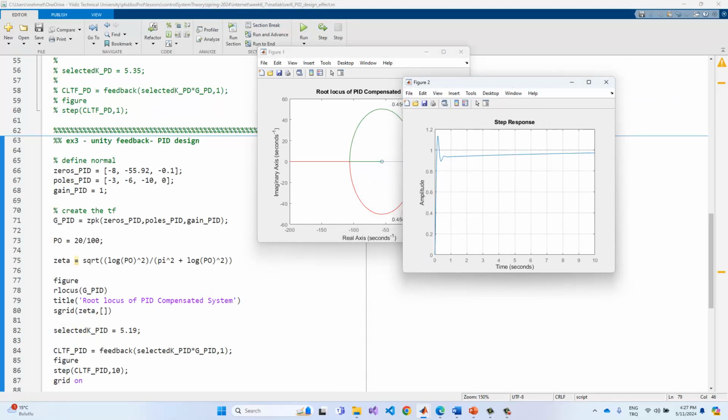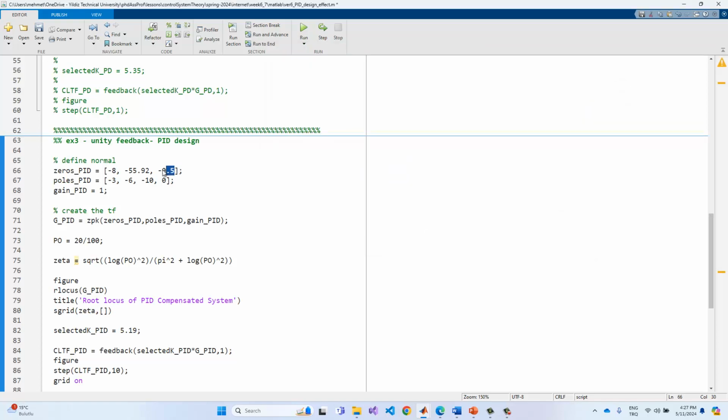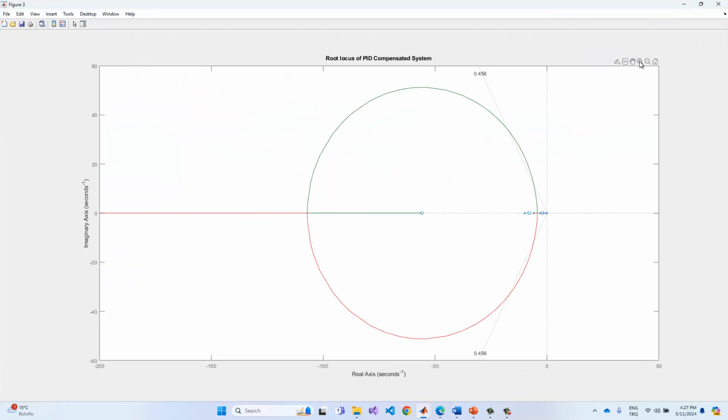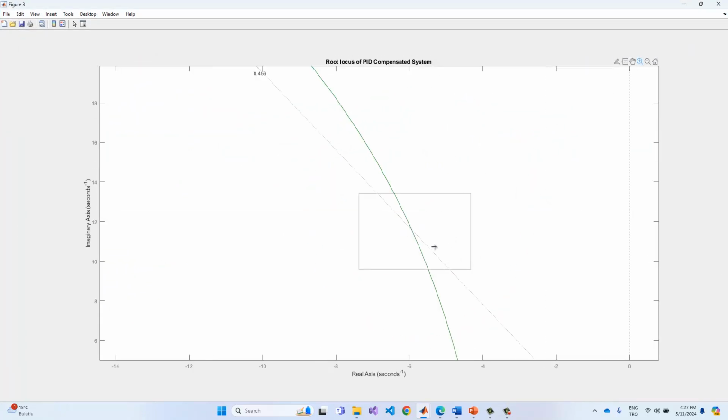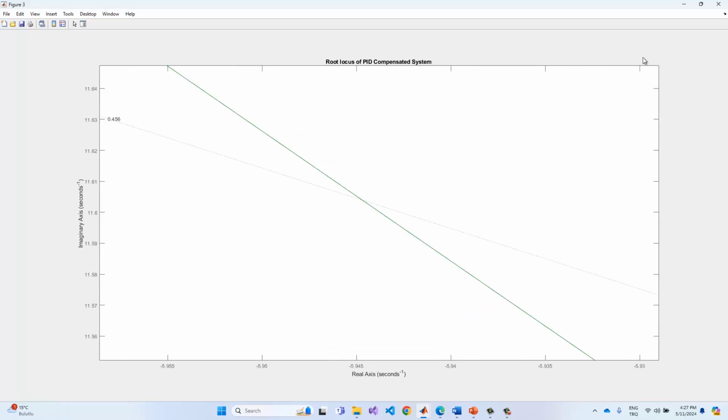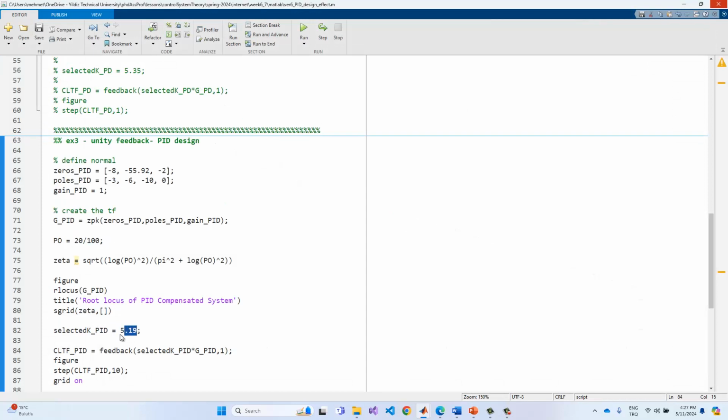And so if I choose to increase the values, the normal condition is minus 0.5, and so if I put minus 1 or minus 2 for the PI controller, and then rerun this code, then we need to select the new coefficients of the K. Just see that I iterate my solution based on this information. I can design it anyway in here. And so the gain must be equal to what? The 3 in here. Okay, and so if I choose 3, and then rerun this code,